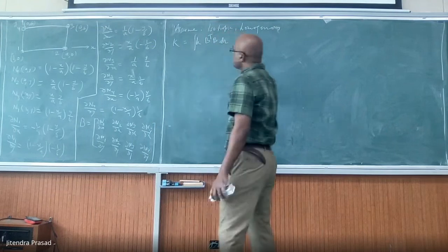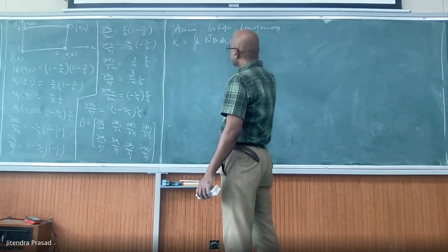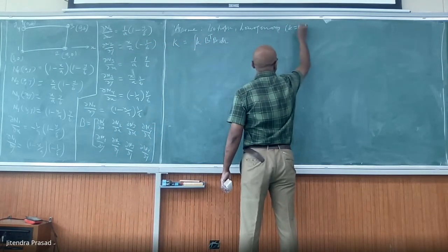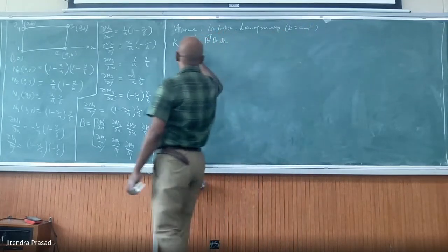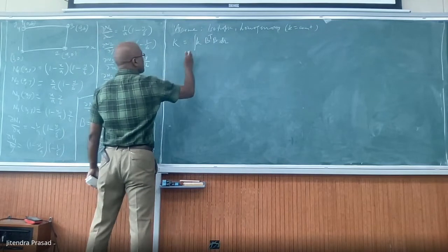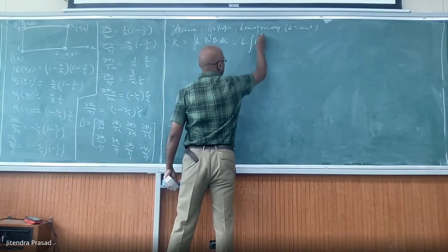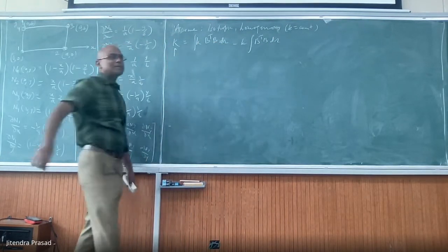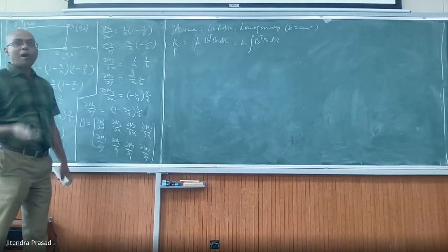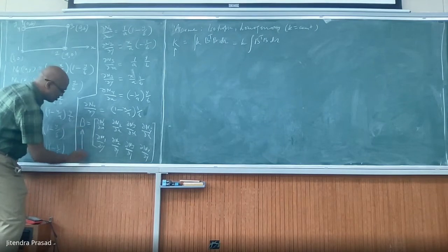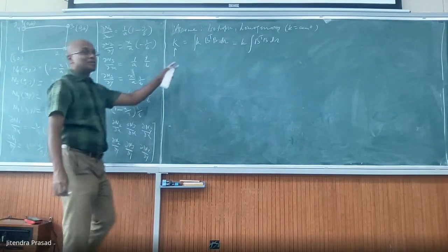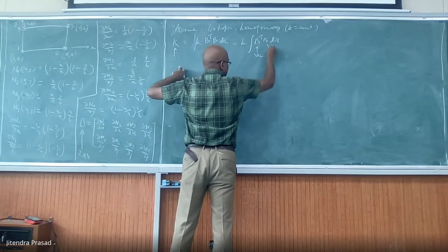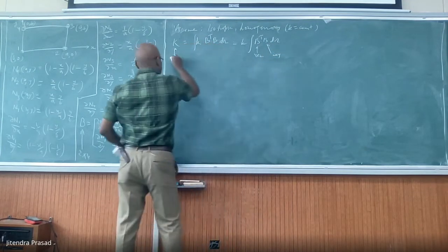So K equals integral of B transpose B, and that really means homogeneous, that is K equal to constant. What is the size of K? B is 2 by 4, so B transpose is 4 by 2. So 4 by 2 times 2 by 4 gives 4 by 4. So K becomes 4 by 4.